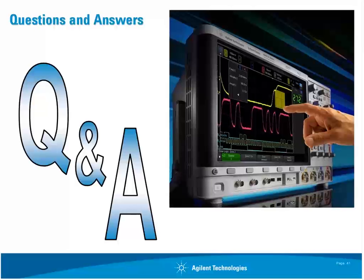The biggest one is where you set your time-based range. If you set your time-based range, let's say, at 1 millisecond per division, that means it's going to capture 10 milliseconds across the screen. You have an acquisition time of 10 milliseconds. And even if the scope had 0 dead time, the absolute maximum update rate the scope is going to have at that time-based setting is 100 waveforms per second.